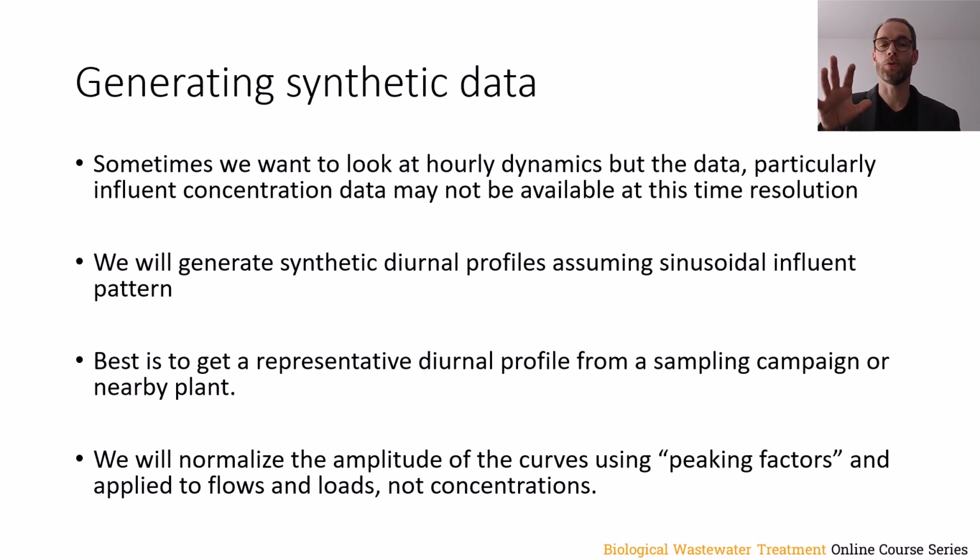So if we want to simulate that variability on an hour-to-hour basis, we're going to have to generate a synthetic data set. And we're going to do that assuming a sinusoidal influent pattern. So we're just going to use a math function and apply that to our data set to generate hourly or diurnal time variability.